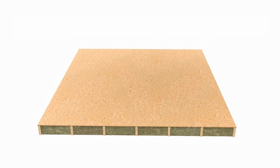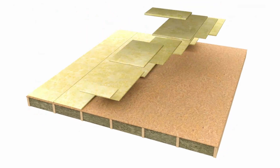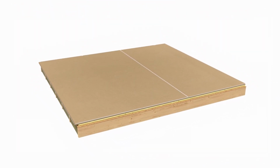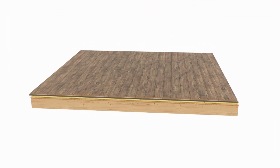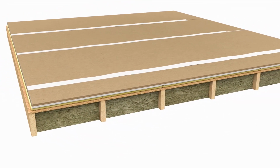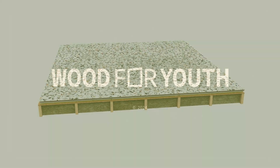In the case of higher sound insulation requirements, an acoustic class wool board is used, which is covered in 2 layers with floor gypsum boards, less often with a concrete board. Either parquet or some roll material is installed on the boards. In the case of roll materials, the surface of the boards must first be covered with a putty mixture and sanded. Then, the roll material is glued.